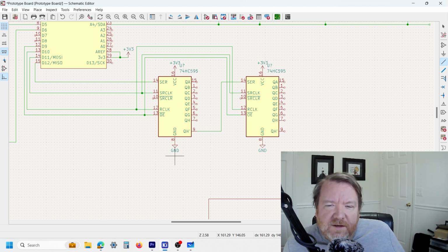I just wanted to go into showing really what it does, but in concept, if you want to control or set digital output pins, and you have a limited number of I/O pins available on the microcontroller, this is just one way of expanding the amount of I/O pins that you have.